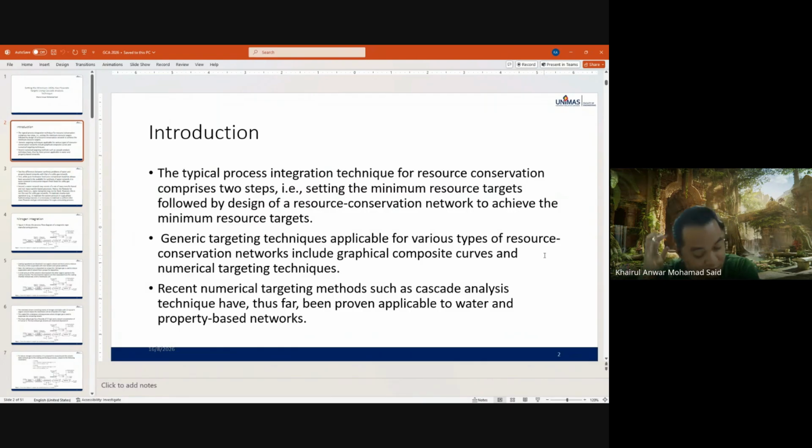The second reason is fixed sink flow rate and operating pressure. A water sink flow rate can often fluctuate as long as it transfers the targeted mass load of contaminant. In contrast, utility gas systems such as gas phase hydrotreating or chemical reactors represent continuous, rigid, volumetric operation to maintain uniform steady state operating kinetics and system pressure. Each gas consuming process must be supplied with a strictly uniform inlet mass flow rate and gas concentration.